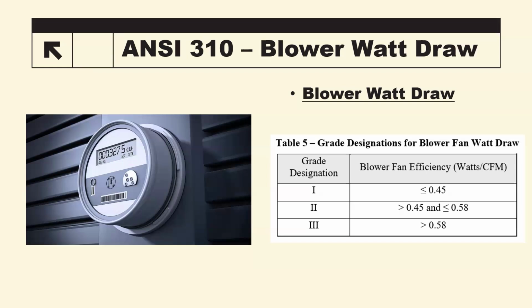Therefore, and I know I've harped on it in many, many webinars before, and I usually do it with my in-person presentations, when you go in the attic and you see poorly installed ductwork, that's a big red flag to me. Somebody's got to correct this. Otherwise, more power consumption, and you're increasing the wear and tear on the system itself, reducing its longevity.